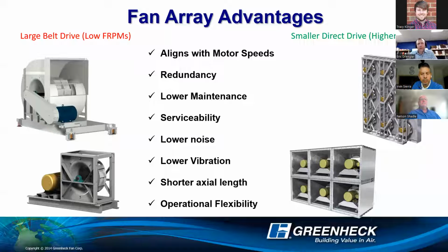You've got multiple fans running, so if a motor goes out, the rest of the fans can maintain airflow, and you can size them to ramp up to maintain 100% airflow with one or two fans down, where one large fan with one motor, if that's down, is down.